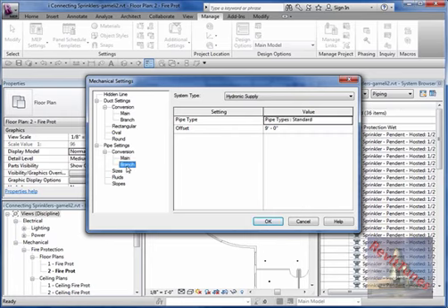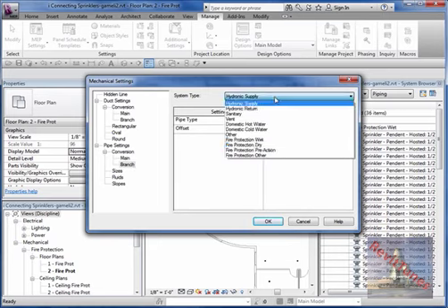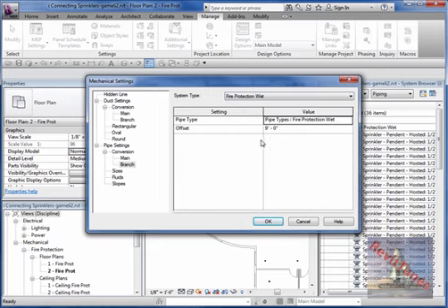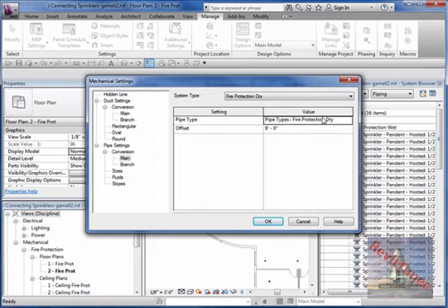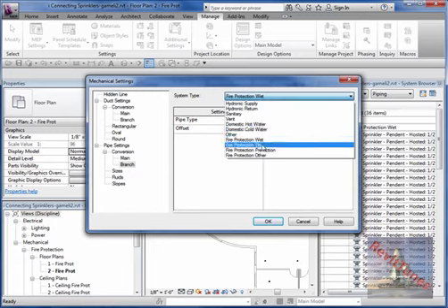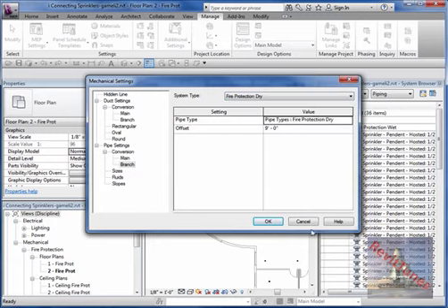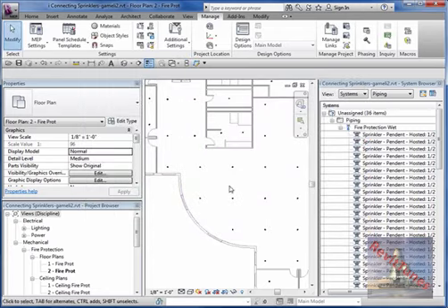And for my branch, again in the wet system, it will be fire protection wet and 9 foot above. And let's go to main, but now dry. Main dry should say dry here and 9 foot, and branch dry should say dry and 9 foot. So I say cancel because I didn't make any change, I was just verifying.